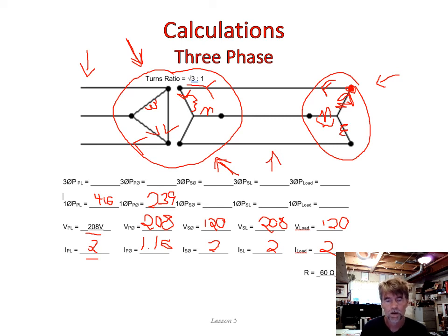Okay? Here's the solution that I want you to fall into. When you're looking at this dilemma and you say something's not right and I'm not sure what it is, here's how you figure it out. Where is that work actually being done in this circuit? The answer is at the load. Our transformer, our primary and our secondary, are providing the power, but the work is actually being done by those resistors at the load. So let's calculate our power there. What is our power at the resistors?